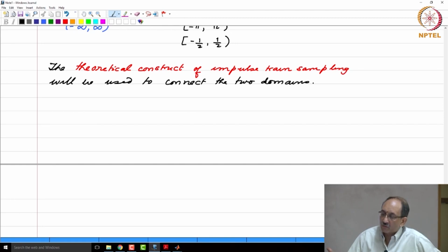And the assumption that you are making when you are sampling and holding is that while you are sampling, the signal is reasonably constant, and if the signal varies too rapidly, even this assumption will not be true, all right. So, all physical systems have to latch on to a certain value and hope that value stays as it is before you can assume it has reached a stable value, lock onto it and then convert it to a number of bits. The second thing is, when you convert this to a number of bits, remember the next sample is going to come at you in no time because you are at a very high sampling rate. So, the hardware has to respond, has to convert this into bits and then be ready for the next sample to be converted. So, all of this puts a lot of complexity and cost on the ADC.